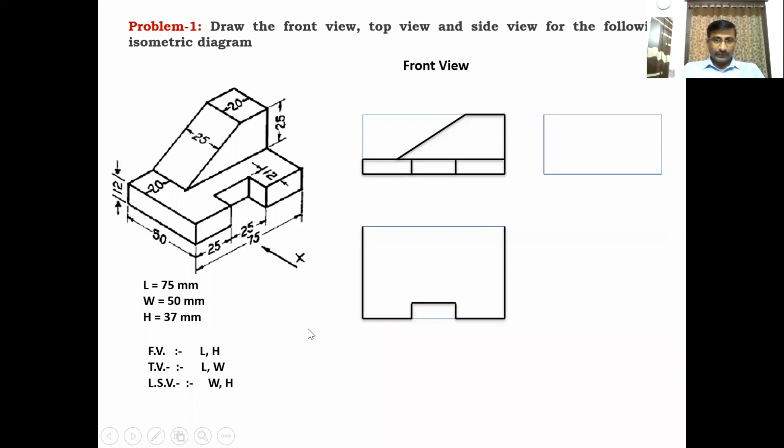This is completely dotted lines on 2 sides, this dotted line and this one dotted line, which coincides with this point, and this is also a dotted line. Completely, this is 25 mm and this is 25 mm. Total 50. Width is 50. Clear? So after getting these 2 lines, join those 2 lines with a horizontal line from this point to this corner.